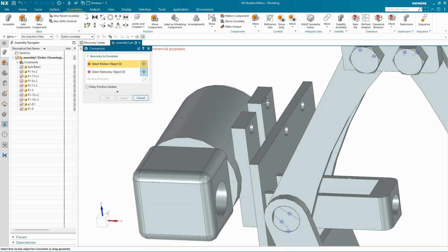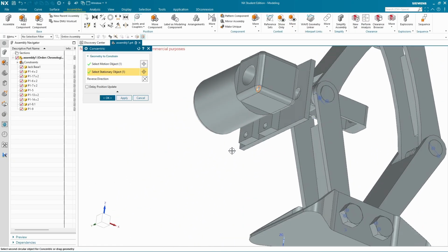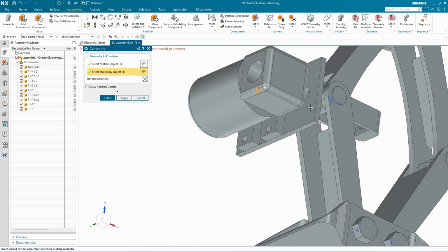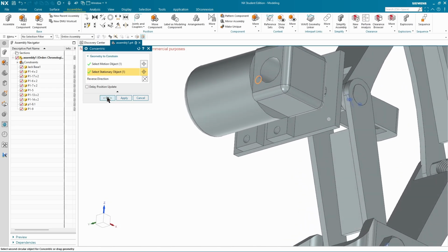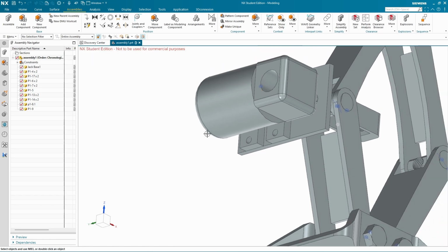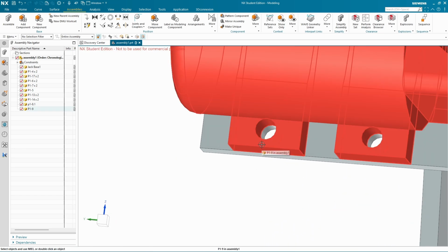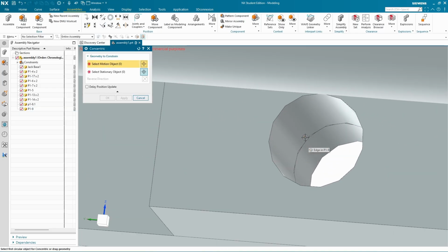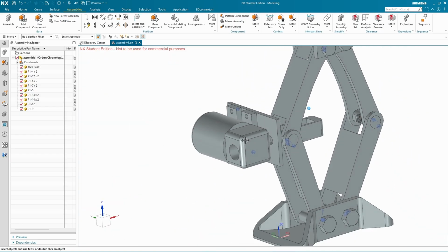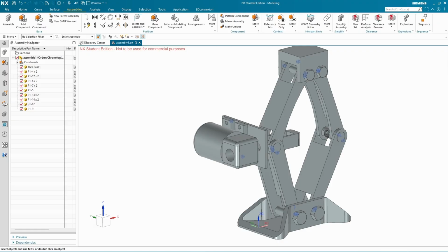So this bolt with this, okay, and it has the option to rotate, so we don't want it to rotate, so we can actually do one more if we want, that way to lock it in position. So let's go this guy, and we can go this edge with the other edge, so there should be two edges there and it locked it in position, so this should not be able to rotate. Okay, let's go back to PDF.